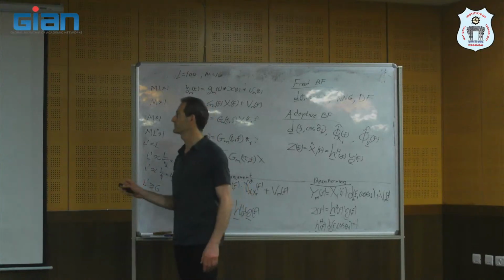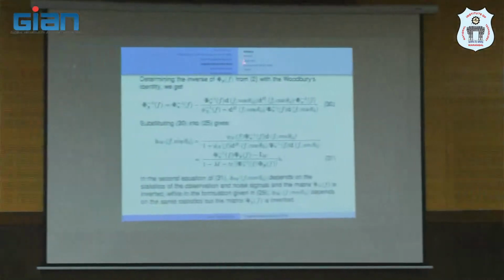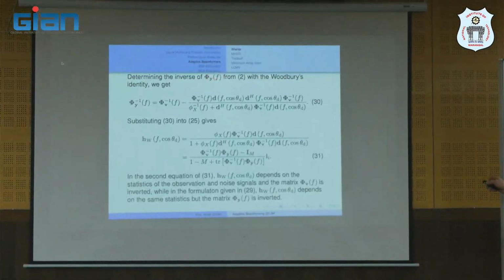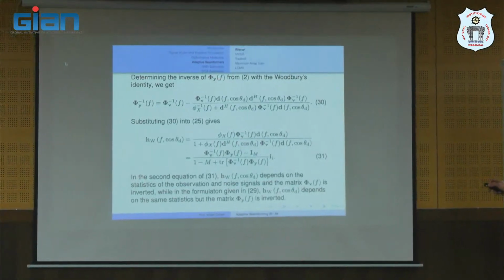Okay? Wiener filter. Then also we have MVDR. No distortion in the environment with no reflections. If the environment that we assume here actually contains some reflections, of course, we can get some distortion. It's okay. But we design everything with beamforming for free field, no reflections. So we have MVDR, trade-off, maximum array gain, okay? Maximum SNR, it's array gain, and LCMV.